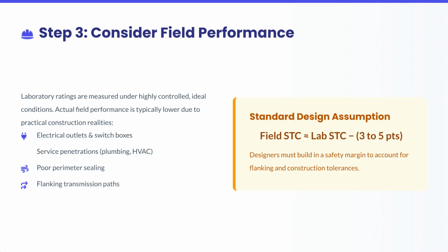In Step 3, we consider field performance. Due to construction realities like electrical outlets, service penetrations, and poor sealing, field STC is typically 3 to 5 points lower than lab STC. Designers must include a safety margin.